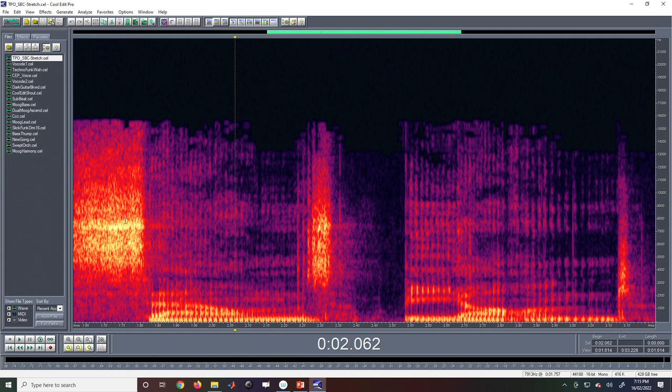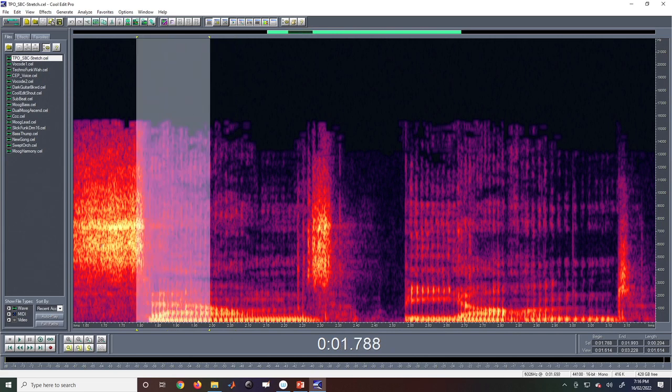So, how do I do this? The x axis is time, the y axis is the frequency, and the intensity or color of the image represents the intensity of the signal. If I represent it in purely black and white, then more black means more energy, more white means no energy. So, this portion will be white and this portion will only have a black line. That is called a spectrogram. But how do I do that?